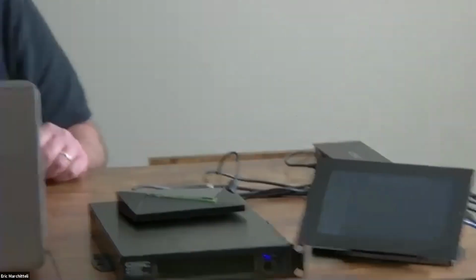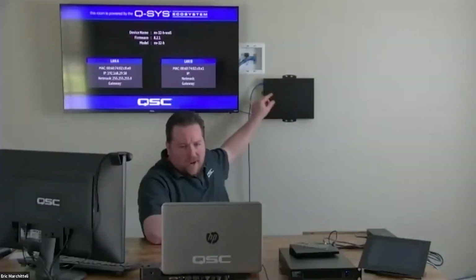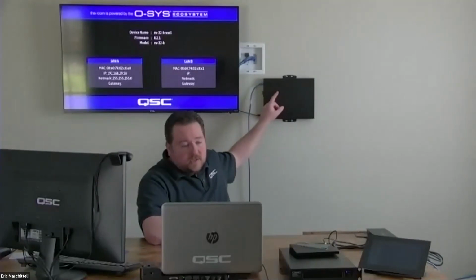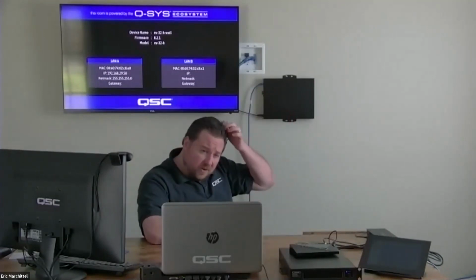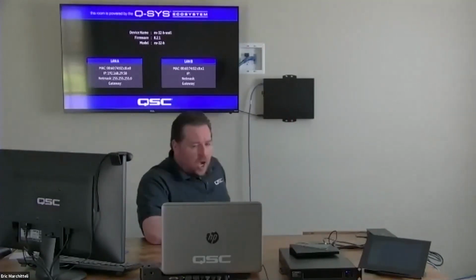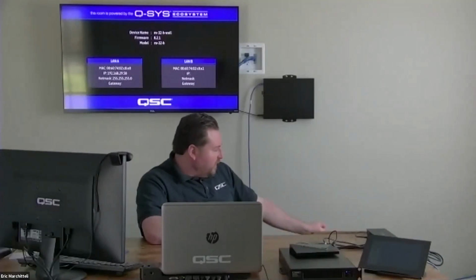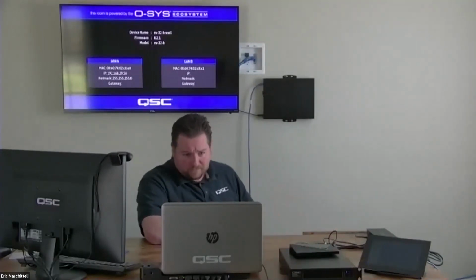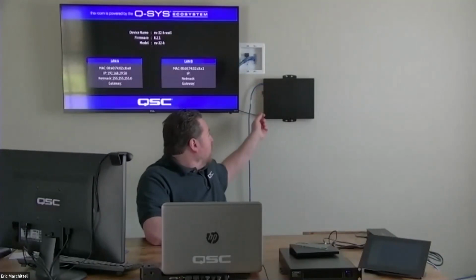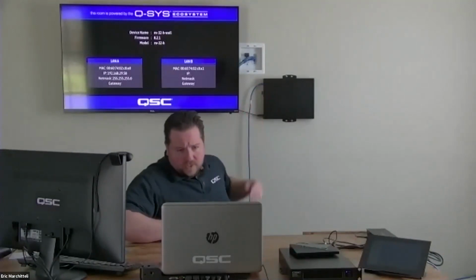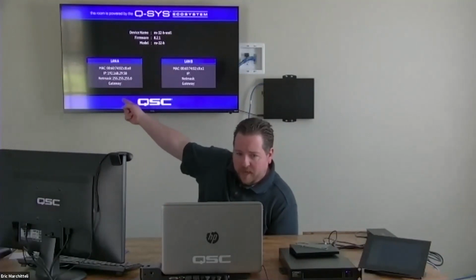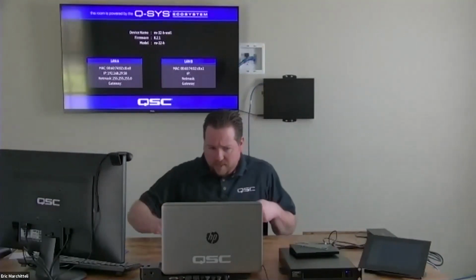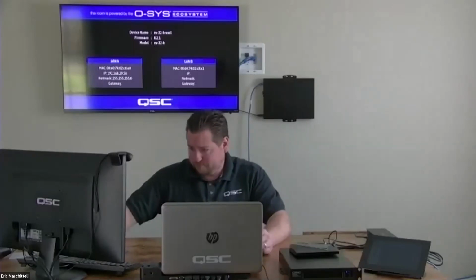And then this one behind me, I'm actually powering via PoE. It's a PoE++ device, meaning it won't work with regular PoE or PoE+. It needs the newest standard, PoE++, which is a pretty beefy injector that I have powering that. So that is an option too. That just has a network cable and then a single HDMI out to the display behind me. And you can see it's already outputting its default image showing its IP address and its system name and everything. So that's helpful when you're installing it.